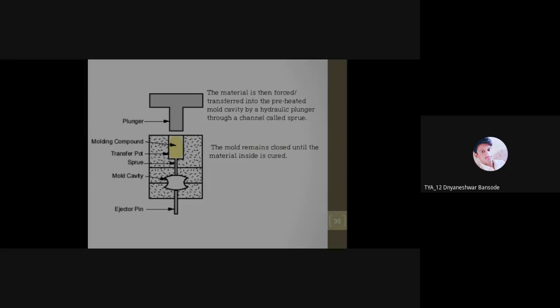Another thing is that we are going for preheating. So thermal sensors can be used. Again, heating is not done randomly, a proper temperature range is required. So this can be done by using heat sensors. Getting it? Heat sensors can be connected with heating elements. So here also we have heating elements with a feedback mechanism. The feedback mechanism will be given by thermal sensors. Getting it? Here also you can provide automation.